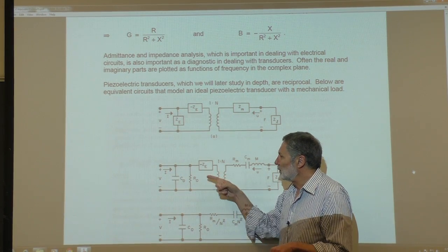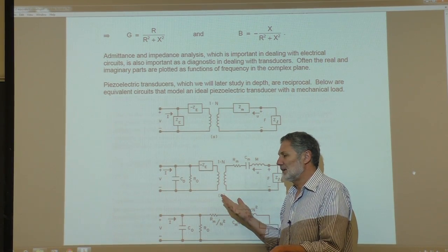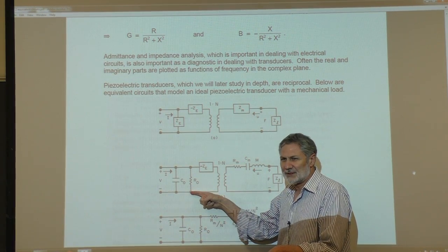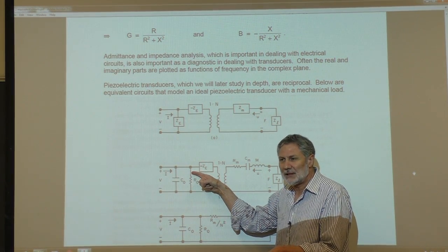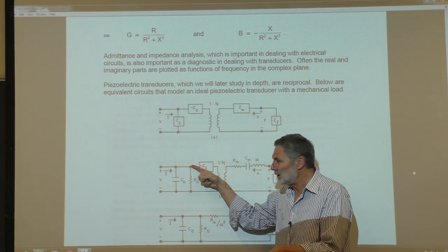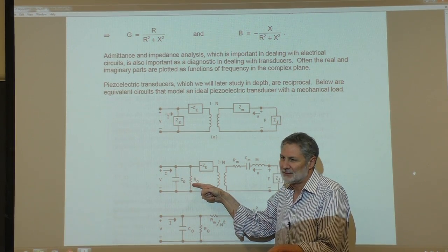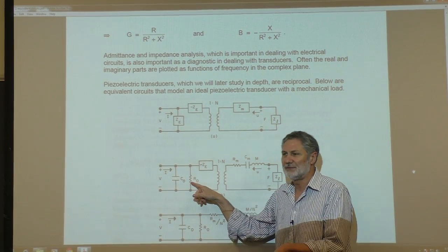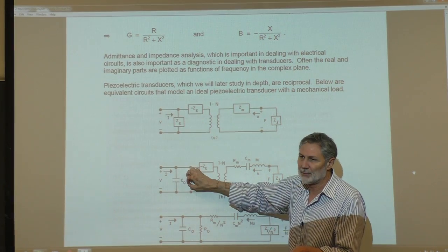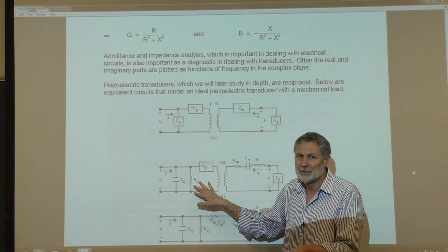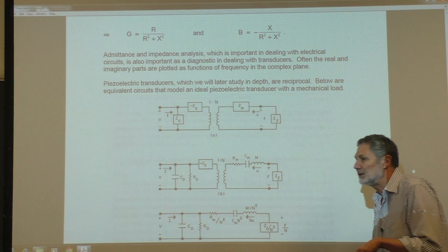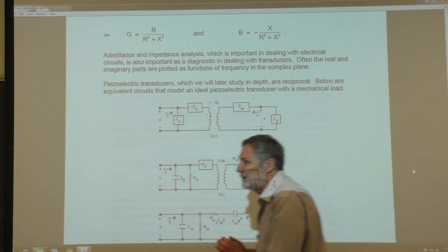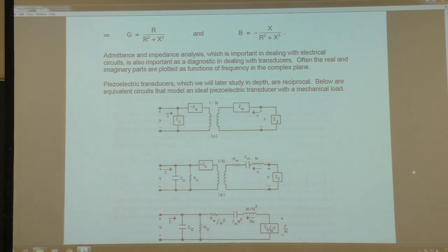And to make it a little bit more realistic, what's this? It's a leaky capacitor, right? If you charge this up, this will cause it to discharge. Almost always, this is a very large number, and often we just forget about it, but he's put it in here just to be general. So that's called the leakage resistance. Okay? The capacitor, for whatever reason, doesn't stay charged. You put a charge on there, it doesn't stay charged.